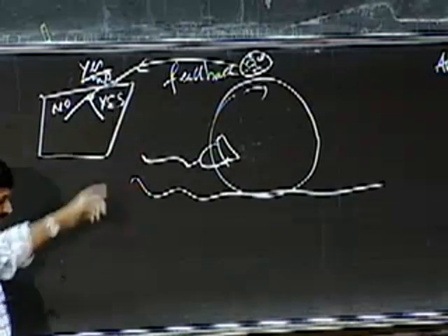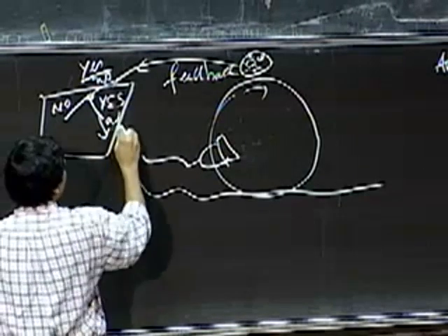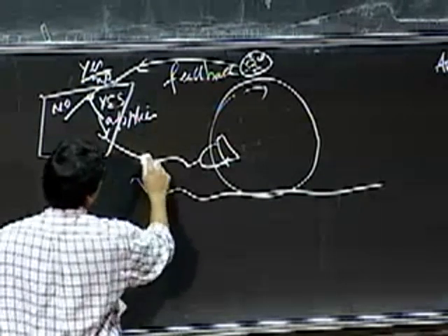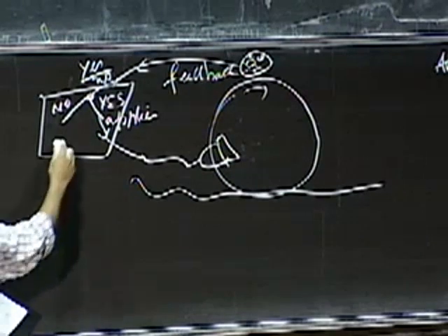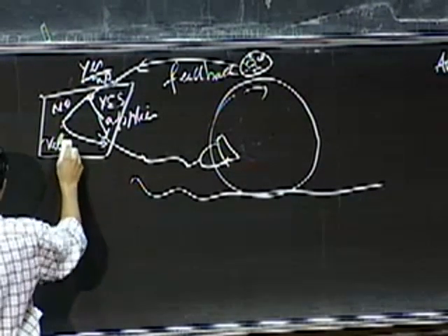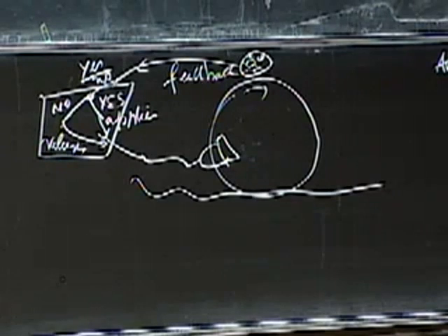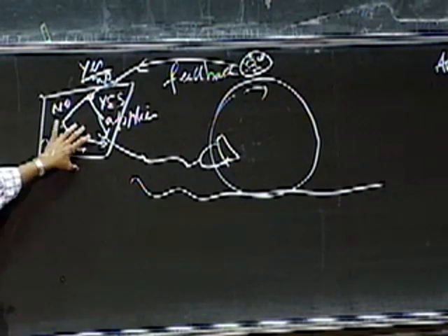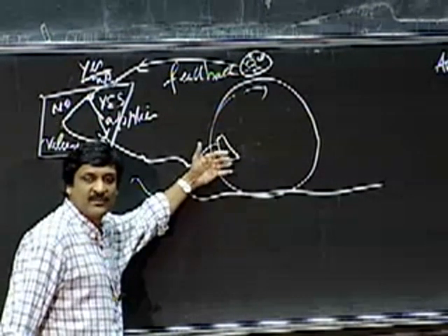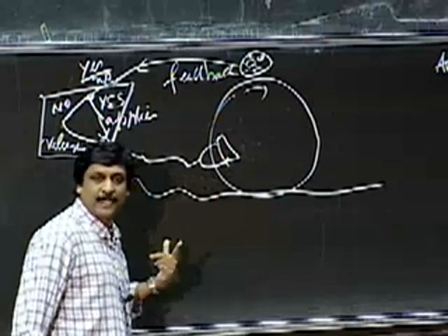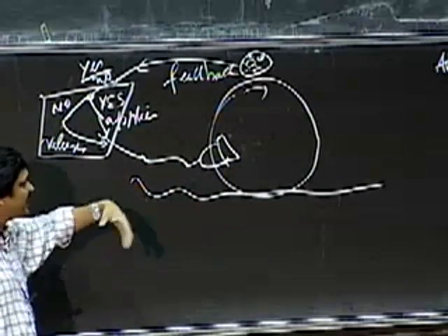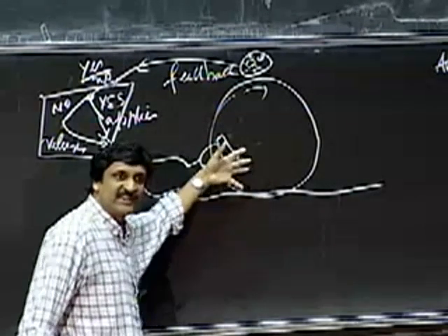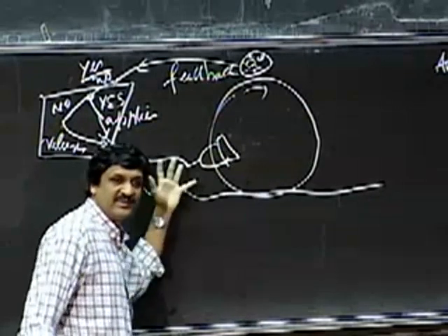If it's yes, then the controller applies the brakes even more strongly. It's turning, so I can apply more brakes. But if it says, oops, it stopped turning, the controller simply releases the brakes. As soon as the controller releases the brakes, the tire loosens up a little bit and starts turning again. This way you're constantly keeping the tire in its region of critical friction so that it's constantly moving, and static friction applies to how hard you can brake. And it doesn't start skidding.